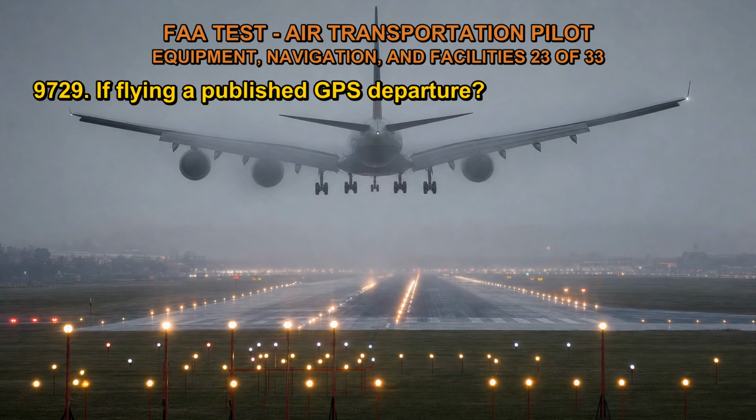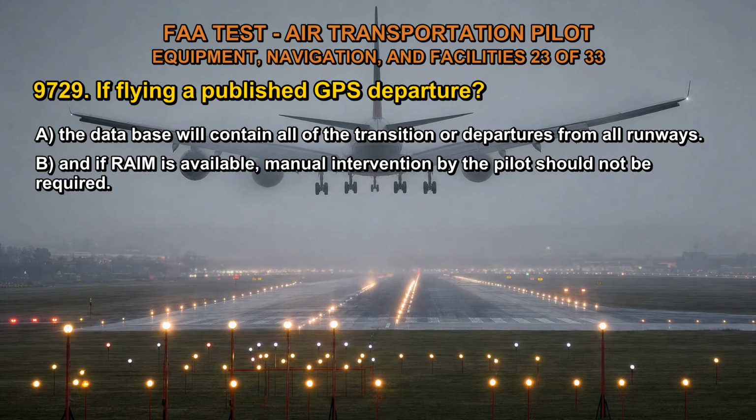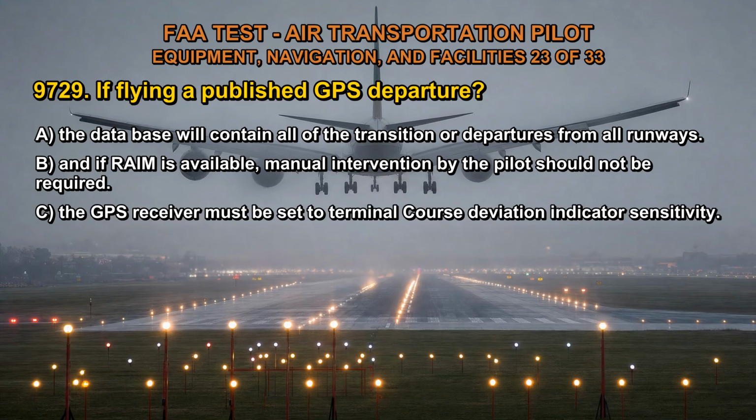Q9729. If flying a published GPS departure, A. The database will contain all of the transitions or departures from all runways. B. And if RAIM is available, manual intervention by the pilot should not be required. C. The GPS receiver must be set to terminal course deviation indicator sensitivity.